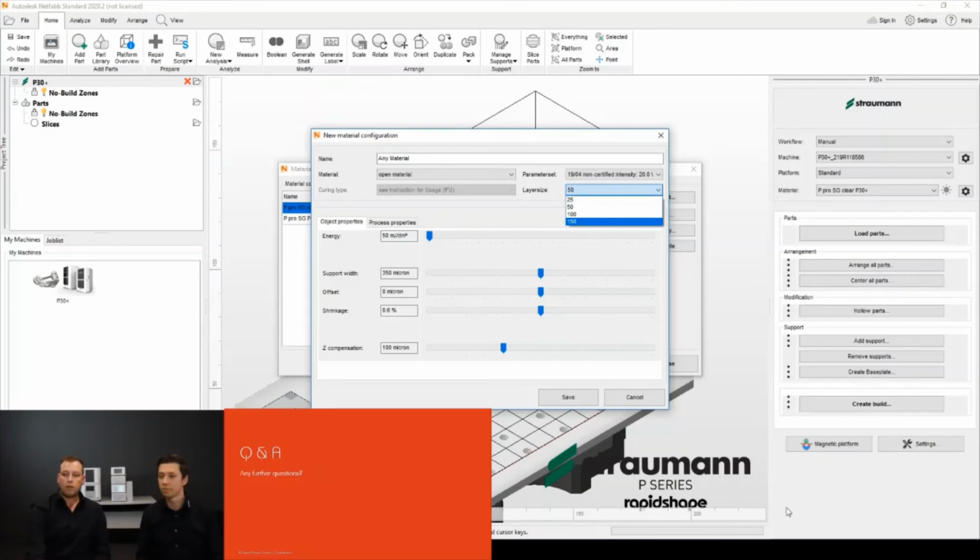If you're going to do this, it's beneficial to start at the low range of 50 and then work your way up. You can imagine that if you just jump straight to the middle and you're printing something really brittle or really strong and it adheres too much to the reservoir, you could possibly damage that Teflon layer, which we have seen in the past, and which ruins the reservoir. So it's beneficial to go from a lower value and work your way up, rather than starting at the top or jumping around. But by all means, it is there to work with.